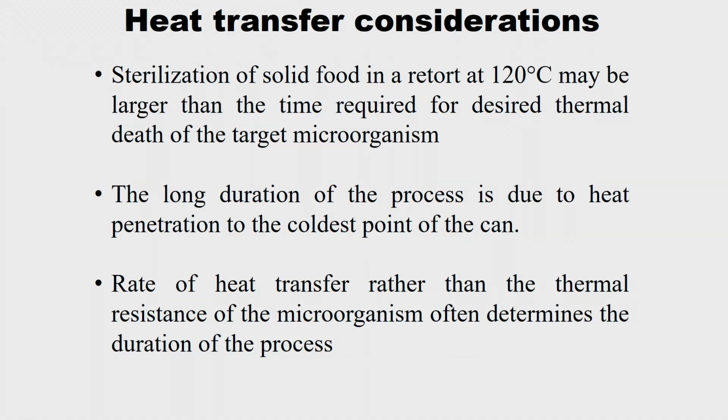So now the second one is the heat transfer consideration. So when I sterilize, what are all the heat transfer considerations I need to take? Right. So normally sterilization of solid food in a retort at 120 degrees may take longer than the time required for the desired thermal death of the target microorganism. So normally what we say is, okay, this particular temperature you need to process at a particular time. For example, in the last example we have seen, if we are maintaining 117 degrees, it should be processed for 6 seconds for the desired thermal death.